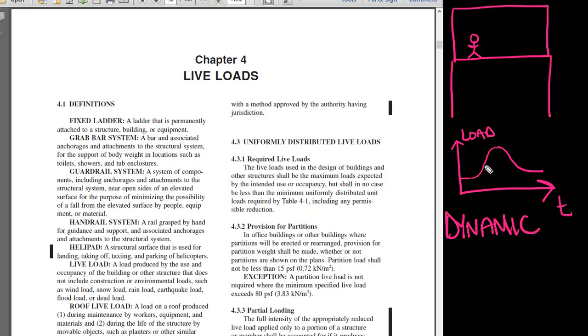But of course, the structural engineer is not going to sit down and analyze every single moment in time throughout the entire lifespan of a building. Instead, they're going to look for the worst case scenario and consider that brief moment in time where a member is experiencing its worst case stress and design for that load. And so structural engineers take what is a dynamic load and turn it into a worst case scenario static load, a worst case single instant in time, and design for that.